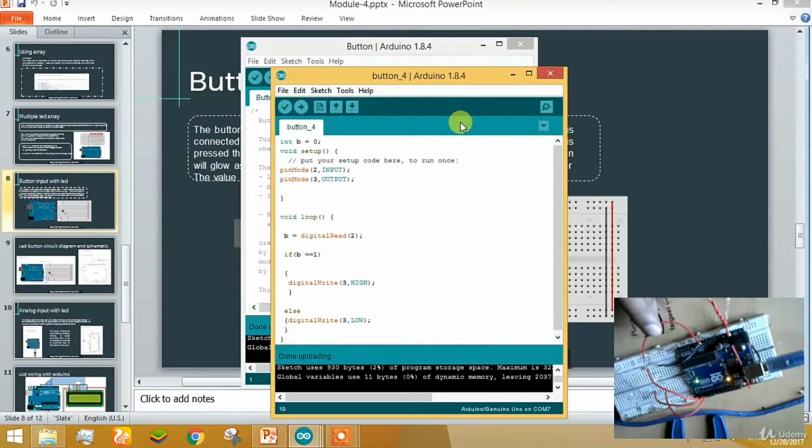Here you can see a wire is connected to 5 volts and this is pin number 2. Whenever we connect this wire, it will turn on high. But remember one thing: because of garbage values, the LED can stay high for a few more seconds. For that we have to connect the pin number 2 wire to ground to get it low. See, you turn it high, you turn it low, you turn it high, you turn it low.